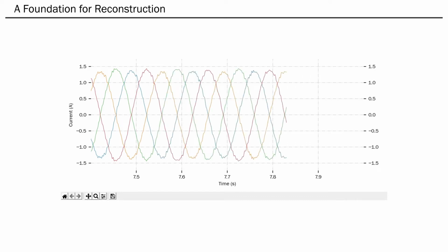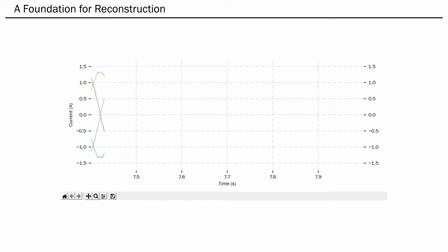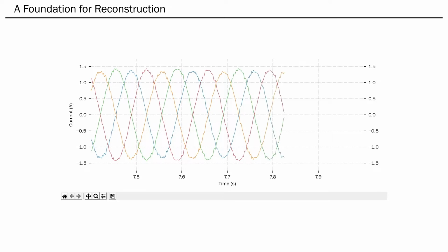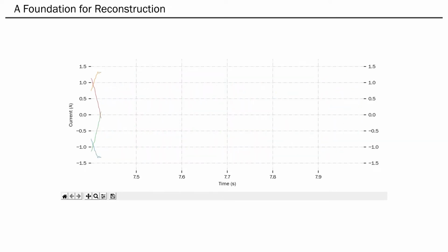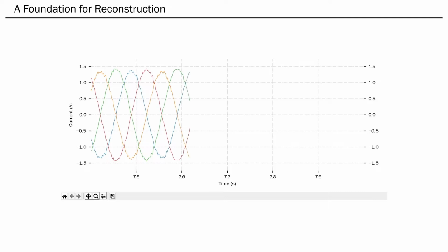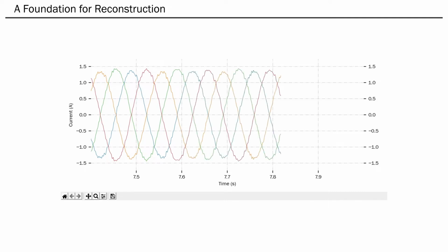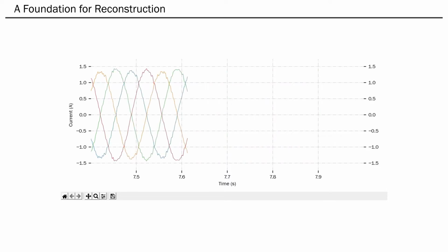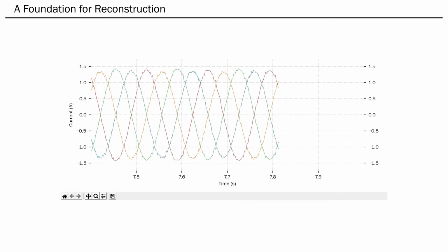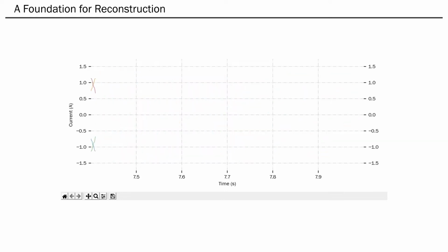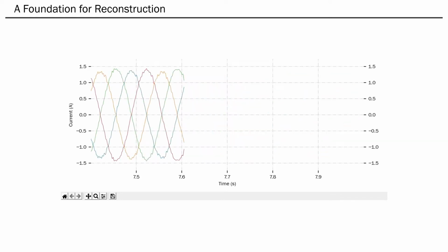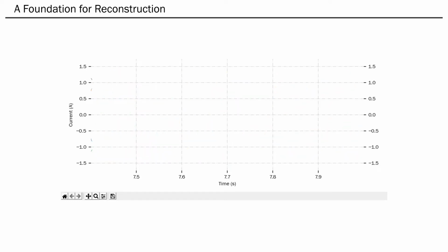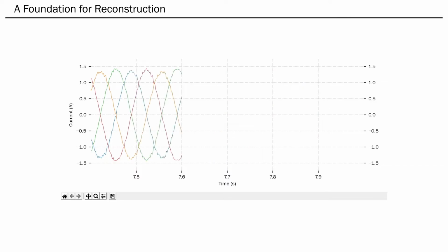This is the foundation of our approach. The current is in direct control of the stepper motors, and the motors are in control of the final object's shape. No matter what security measures you apply to the data, it must eventually be decrypted and used to generate control signals for the motors. A man-at-the-end attacker can intercept those control signals. This traces from our Lulzbot, captured using an oscilloscope with inductive current clamps on the motor wires. The rest of our approach proceeds from here, using captured current data to reconstruct the shape of the printed object.